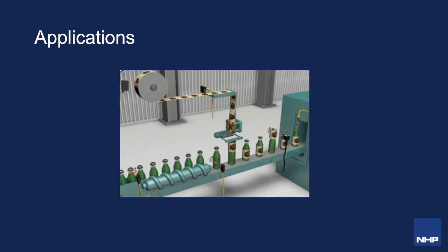So from the picture, it looks like you need to detect bottles and their fill level, their presence, if the label is present and correctly orientated, as well as if there's a cap that's placed correctly. Now you also need to detect when the label roll is low, so it needs to be replaced, and it looks like it's an indoors clean environment from what you can tell so far. So we have multiple points of detection.